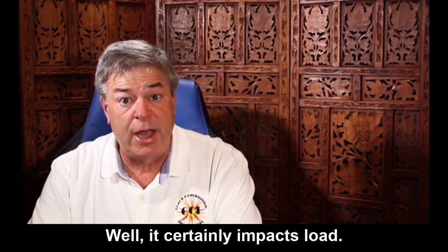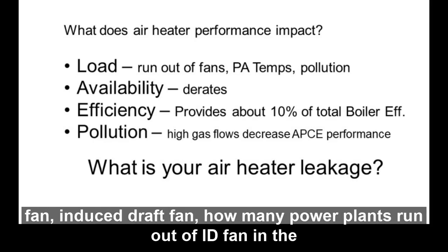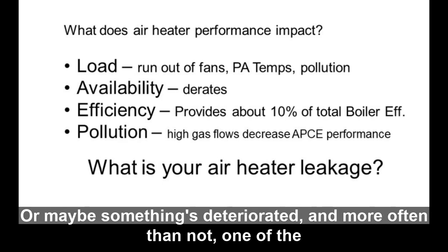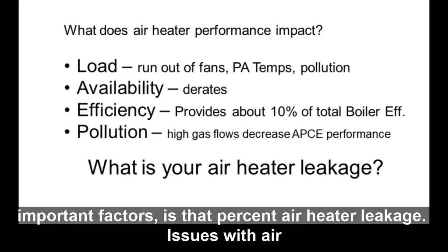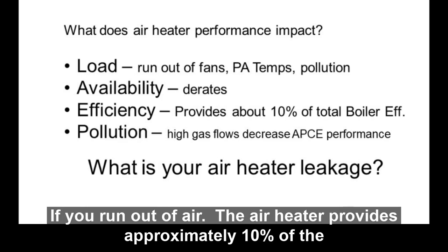Well, it certainly impacts load. I can't tell you how many power plants I've been to that run out of ID fan, induced draft fan. How many power plants run out of ID fan in the summertime? And I'm like, do you think they designed it to be that way? Or maybe something's deteriorated? And more often than not, one of the important factors is that percent air heater leakage. Issues with air heaters and airflow can cause availability issues and derates if you run out of air.